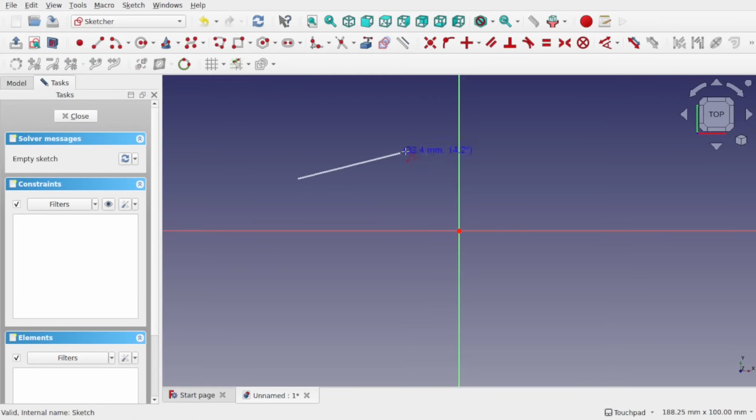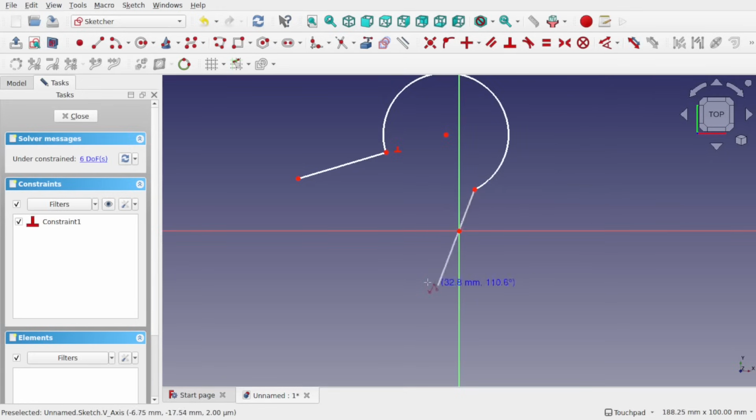So if I click once on the polyline and bring this out and click again, and now if I start using M, you can see I'm cycling through different modes on that polyline. So straight line, a line that goes at a right angle, and then we've got the tangent arc there, and you can see the types of arcs we can get and the different modes we can get by using the M. So this is coming to dimension now. Let's hit the right mouse button to cancel that, and right mouse again.